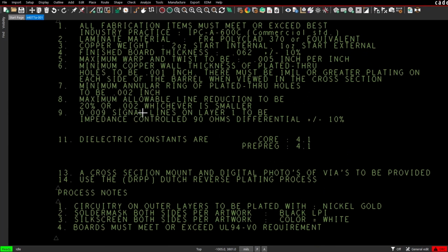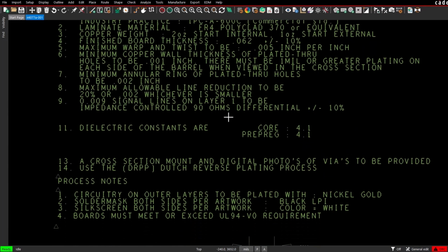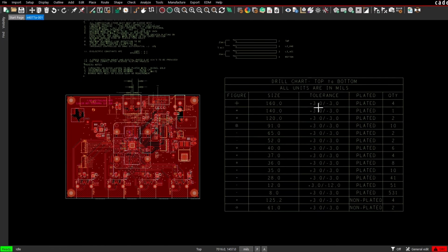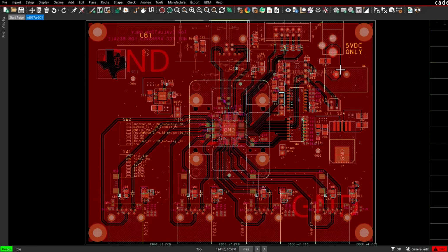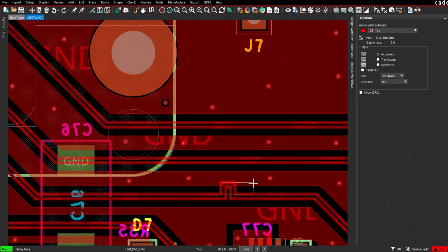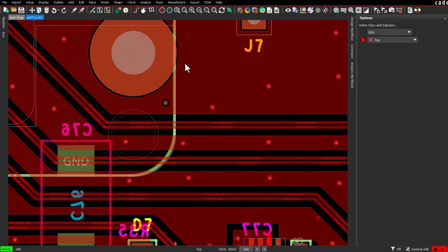They might tell you one thing, and if you don't specify in your design notes that you need a specific dielectric material, dielectric constant and all that, they could pick something, or even a fiber weave, that gives you much different performance than what you simulated for. Then based on your findings from the testing and board bring up, you revise your design and go through a second iteration, but hopefully there won't be a second iteration, because you want to design right the first time.